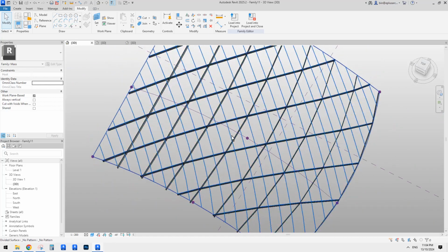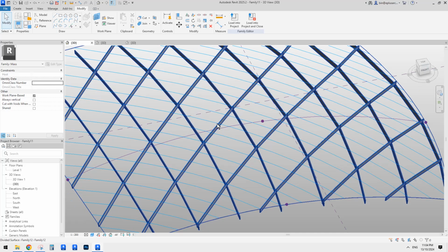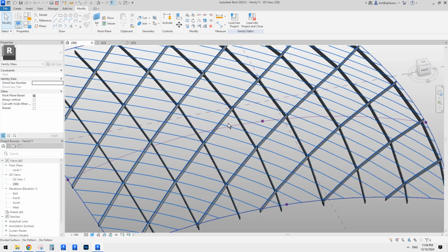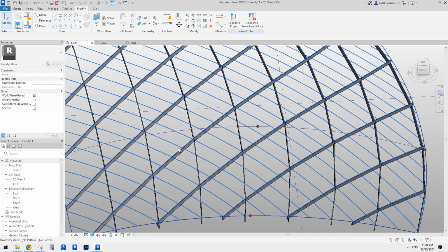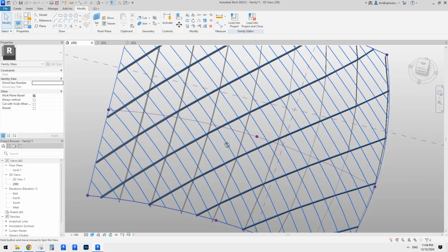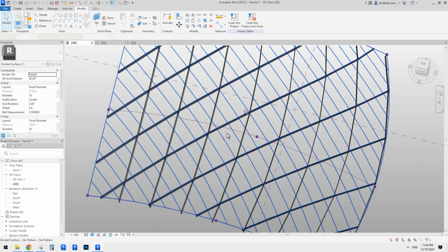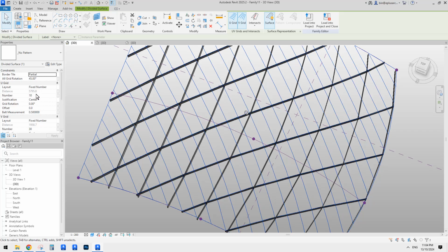So we're not going to create a normal pattern based family for a rectangular shape, or create a form with that form, because it's always flat on that one edge. What we want to achieve is... maybe we need to rotate this grid a little bit. Not sure which one, so I'll try this one. Okay, so maybe 15 degrees.